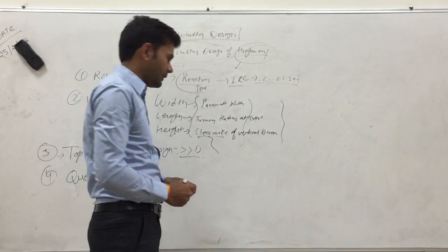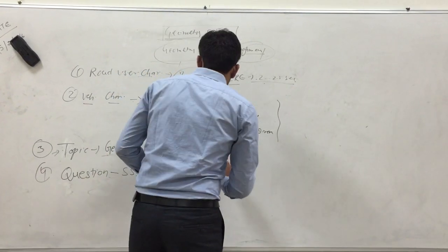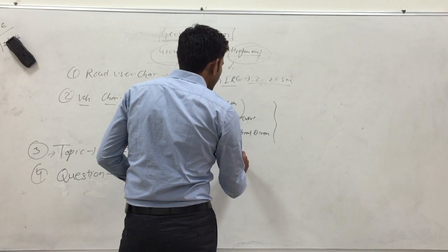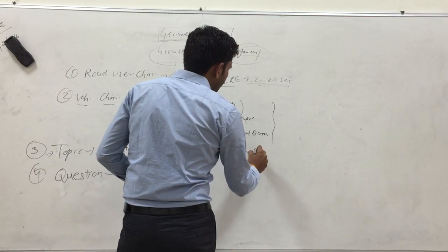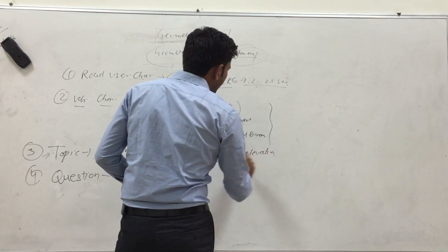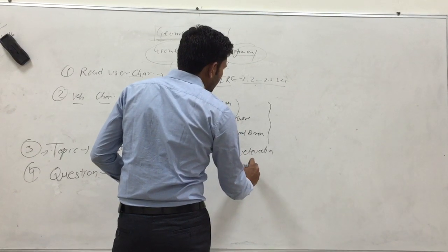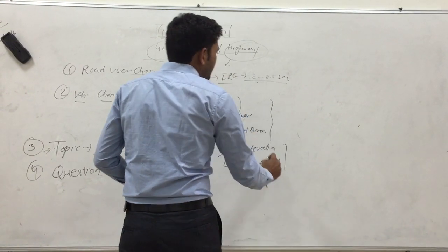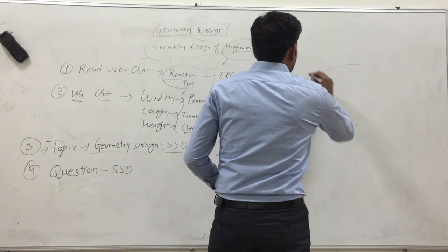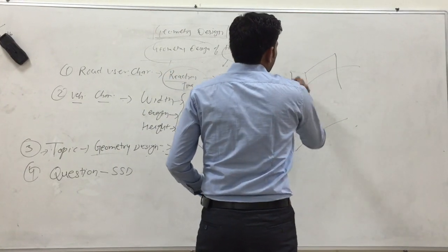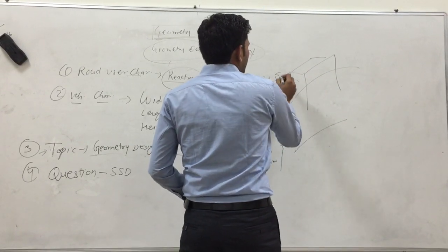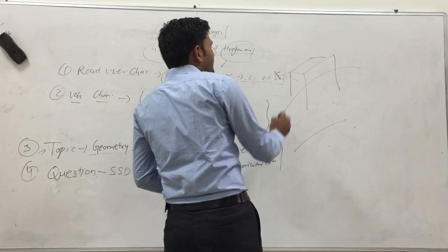It also influences the super elevation, as we will discuss in future classes, which is provided at a horizontal curve. In which there is a force acting outward on the vehicle, which can overturn the vehicle.